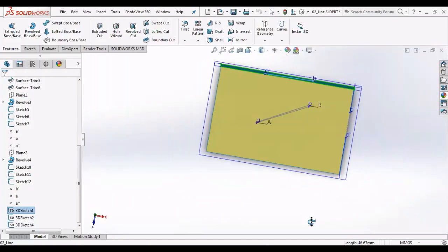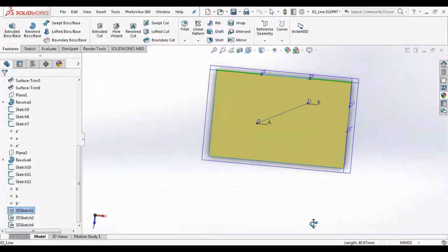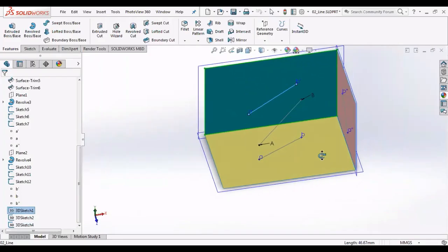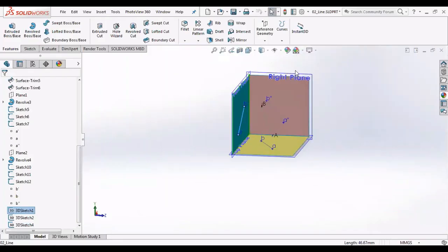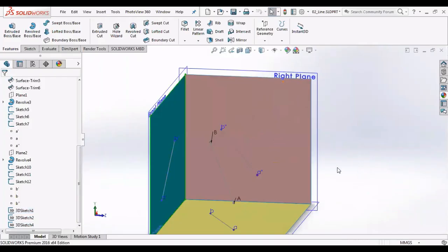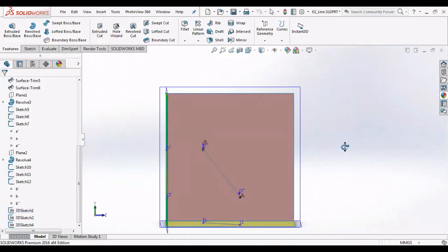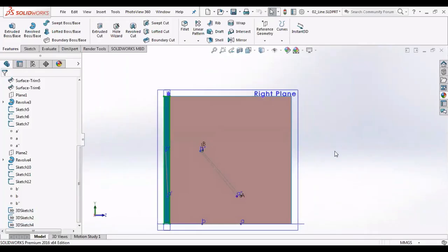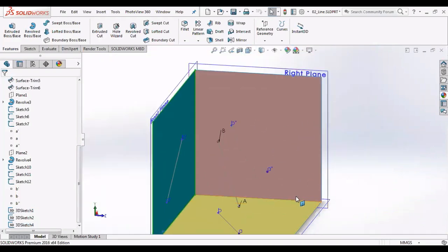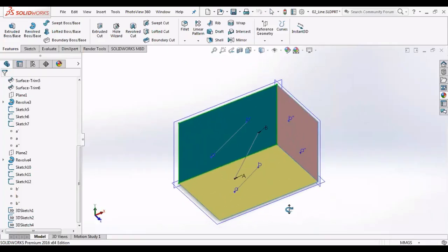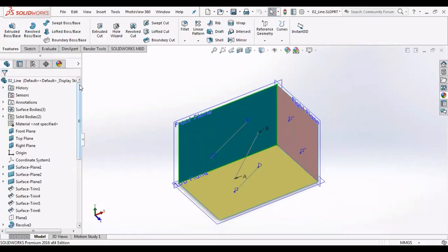If you project it on the top plane, the yellow plane, which is called the H plane, the horizontal plane, we will get the AB line. And then that is a right plane. If you project it looking at 90 degrees to the purple color, we will generate the projections A2 dash and B2 dash. So that is the projections of line AB into the orthographic projections.